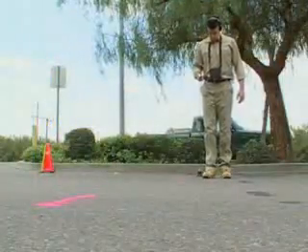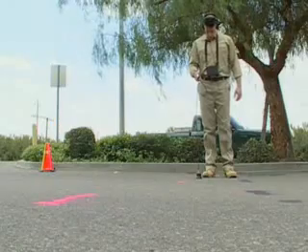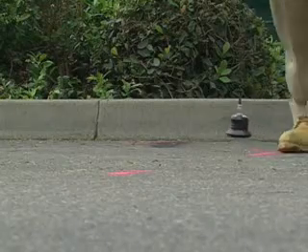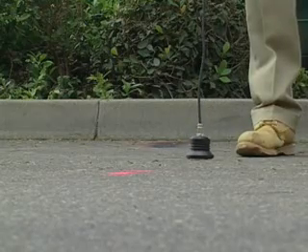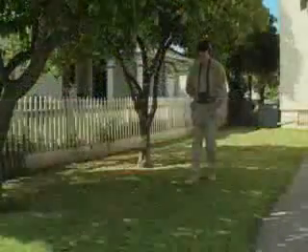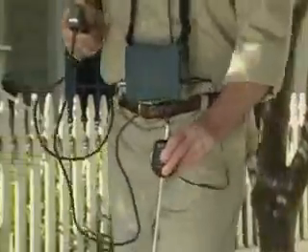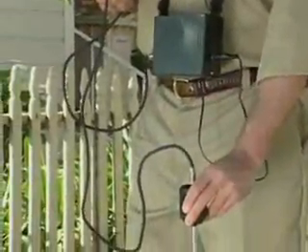The surface material also affects the amplification of leak noises. A hard surface like concrete will resonate with the sound of a leak for 5 to 10 feet around the water pipe, while grass and earth do not amplify leak noise. Select the proper sensor for the surface on which you're locating.